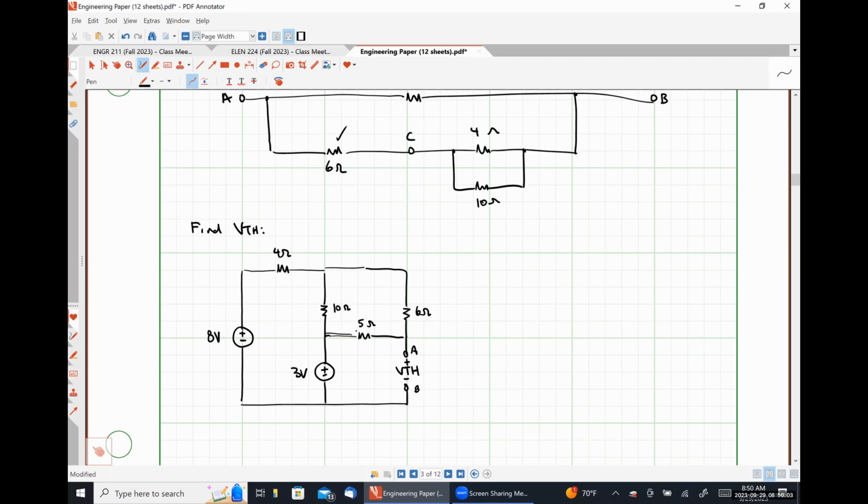How are we going to find that voltage? Nope, because we're finding the Thevenin equivalent voltage, which means we need to be looking at a live network. So there are 6 different paths that I can think of to do KVL for this equation.